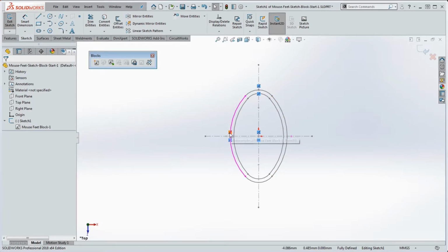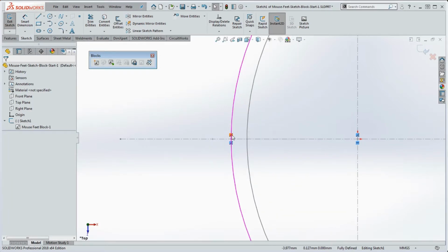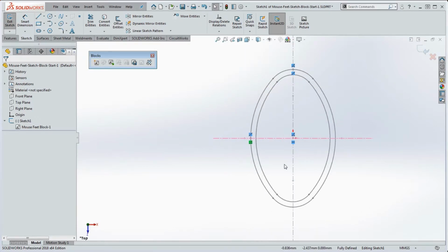So I'm not certain what these relationships are. We have a midpoint relationship in here and a coincident relationship. Let's see what that does. There's a coincident relationship maybe between that point and that center line, a midpoint between this arc, and I can't see the other relationship in here too, but I think if we just delete those, I don't think we really need those. I don't think it helps define our model.